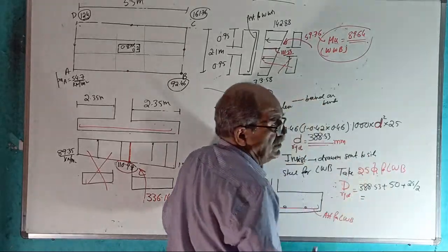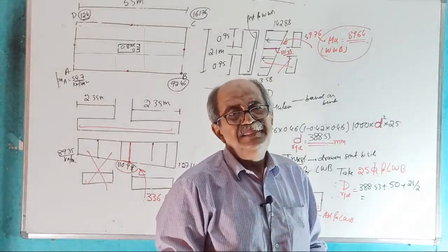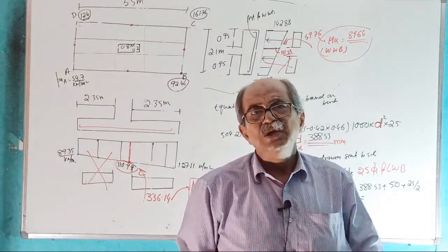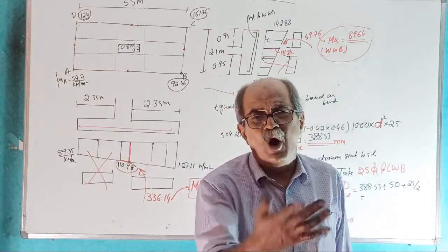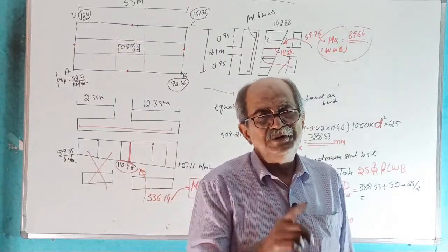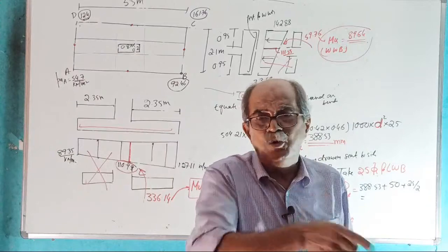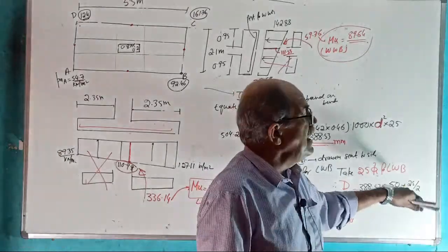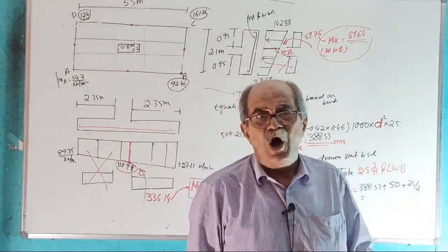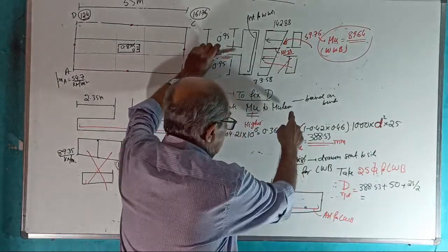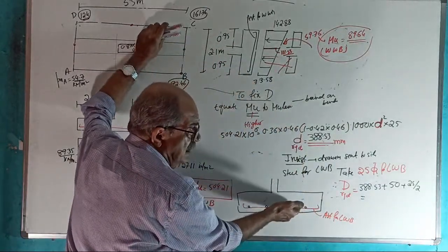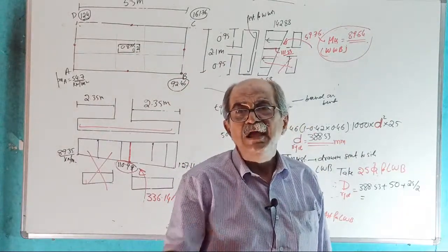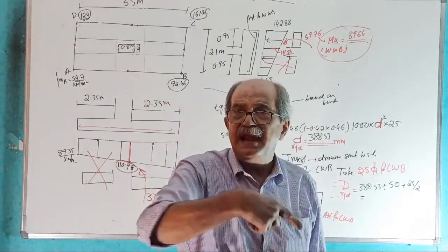Don't take like last time. You insist. Now in the site, they will provide lengthwise bar first, then widthwise bar. If they place it the other way, you need not permit concreting. You tell them, remove it and put it once again. In the drawing I have written, place lengthwise steel first, then widthwise steel, or I will give a section for them. Can't you see this? Sir, usually you provide randomly, then you go randomly somewhere and put your bar bending. Don't come to my site. Get out.